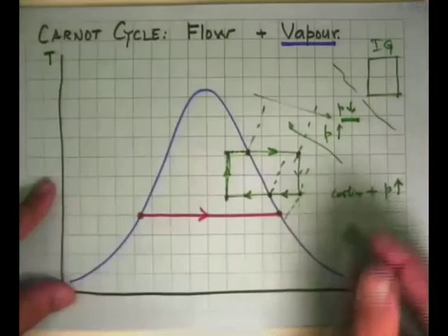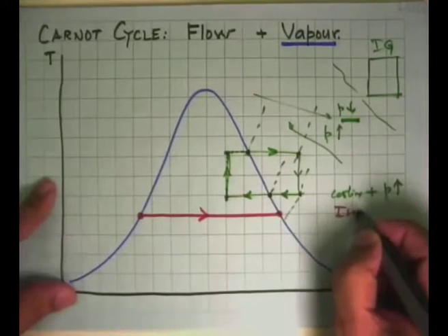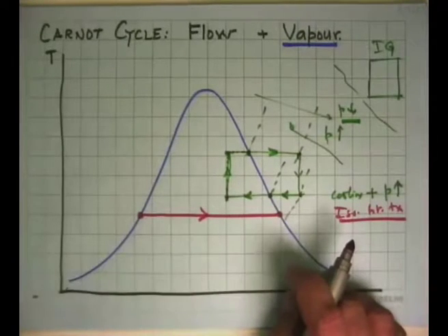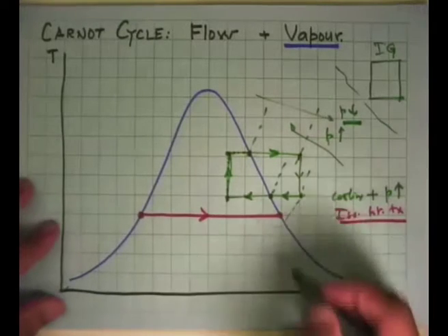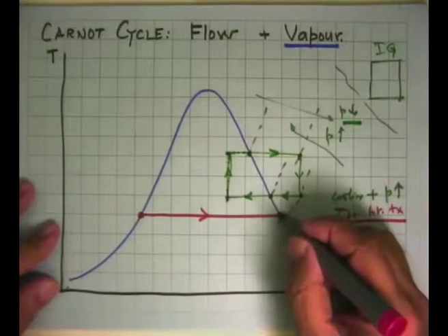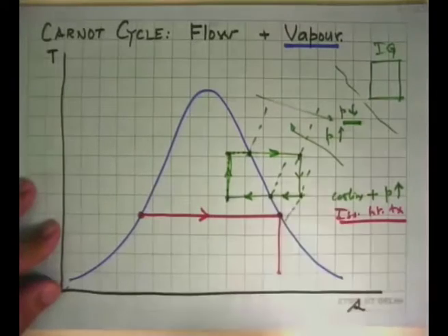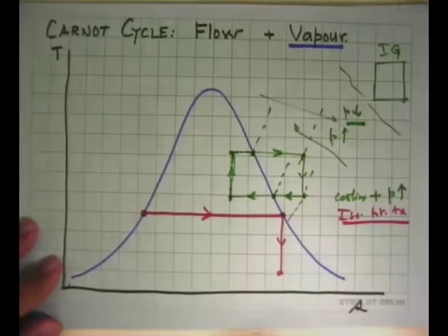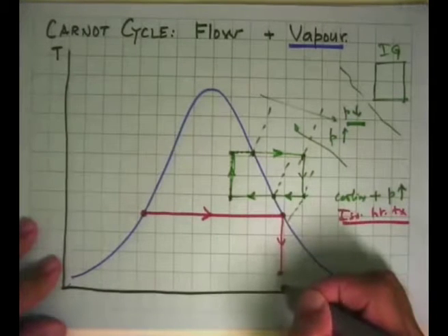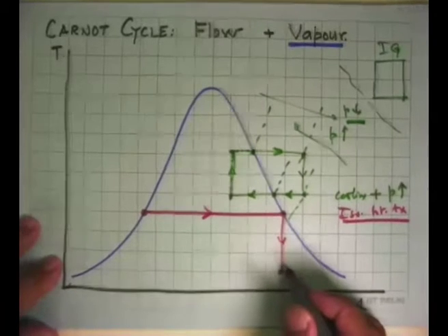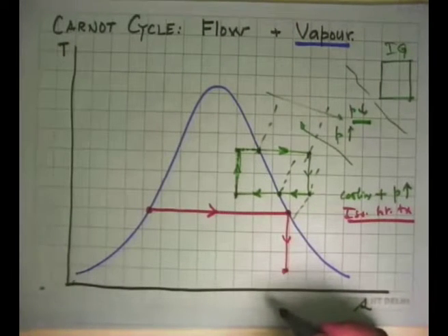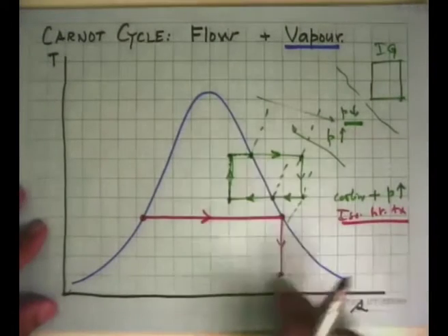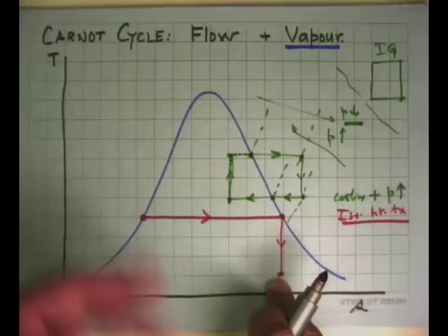So we got two advantages in the same shot, that we got isothermal heat transfer, something that the Carnot cycle wants. We got it. The next thing, we have to have an isentropic process from this point. So this process will come down there. Here we have a little problem, that as you come down, the dryness fraction keeps getting less. So we are getting into a wet zone. But if the dryness fraction is like 0.9, 0.95, it is not too much of a problem. Machines have still been made, they are reasonably reliable. So unless it goes down to very low dryness fractions, then this is not possible.